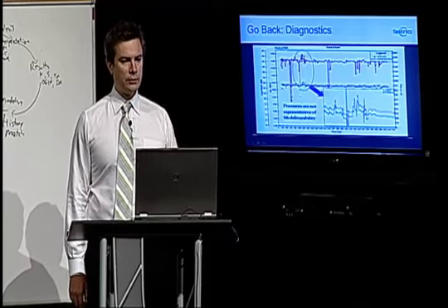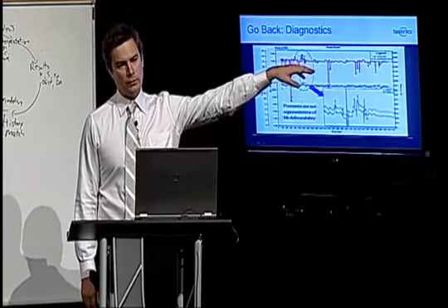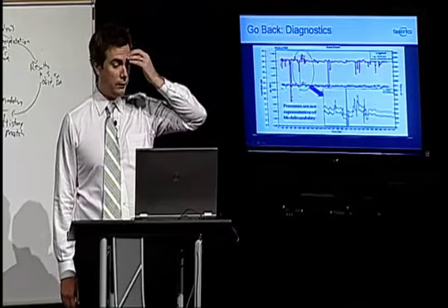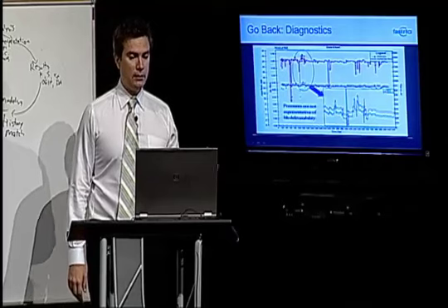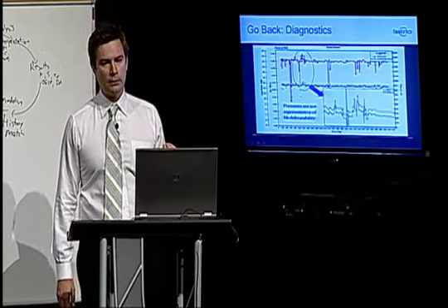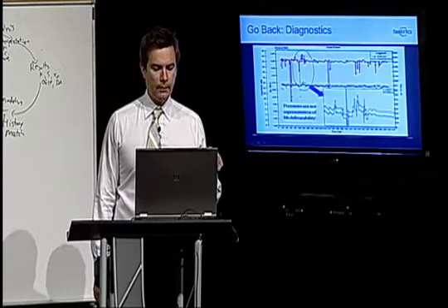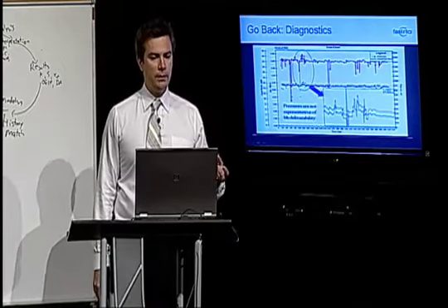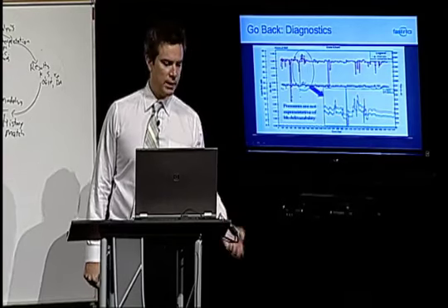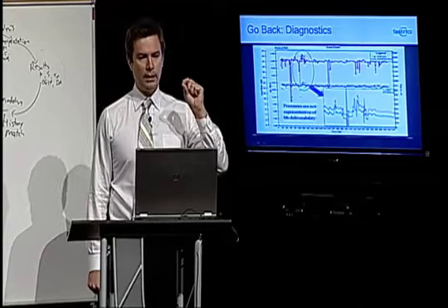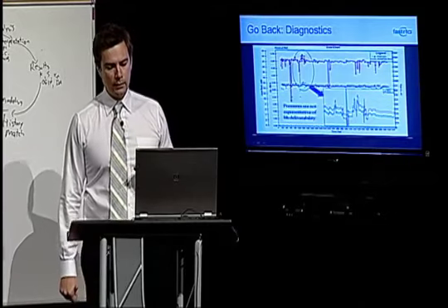If your flowing pressures are far, far away from the source, for example, plant inlet pressures or something way down at the delivery point, the accuracy or the reliability of your interpretation will be very, very suspect. Now I realize that in most cases it's not practical to measure pressures right at the sand face. So we settle with measuring pressures at the tubing head or the casing.